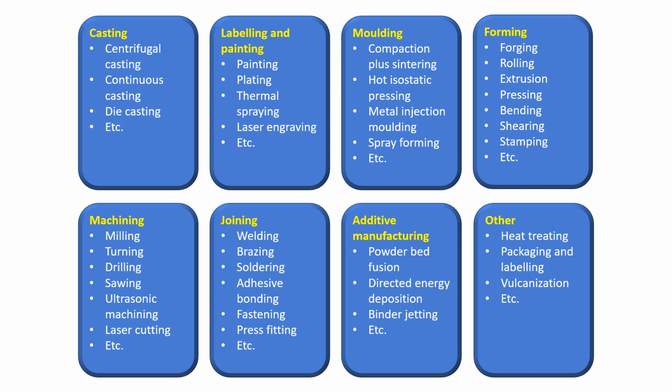Designers have a very big influence on the methods by which a product and its parts are manufactured. The choice of manufacturing methods is, of course, influenced by the cost-effective implementation of the technical requirements. Additive manufacturing differs relatively much from other manufacturing processes, and these differences allow the method to offer unique opportunities and freedoms to design. The general rule of thumb here is that if a part can be manufactured economically using a conventional manufacturing process, it may not be worthwhile to manufacture using AM methods.